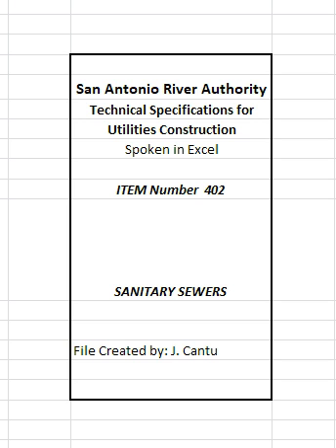Before leaving the work unattended, the upper ends of all pipelines shall be securely closed with a tight-fitting plug or closure. The interior of laid pipe shall be kept free from dirt, silt, gravel, or foreign material at all times. All pipes in place must be approved before backfilling. When replacing an existing system in place, contractor shall maintain screens to prevent the entrance of construction debris into the sewer system.